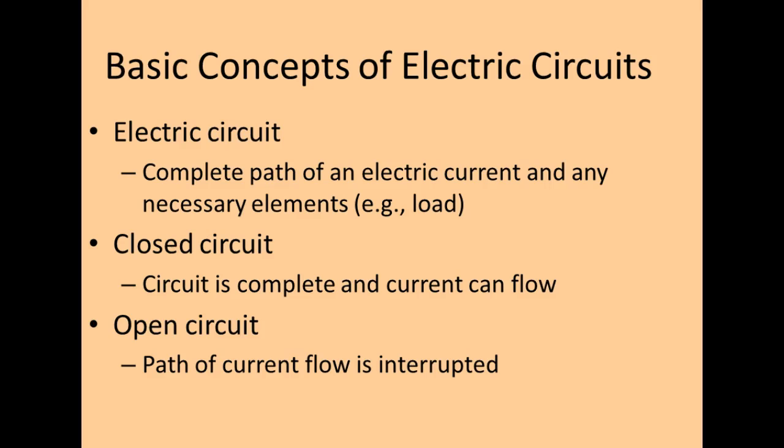There's resistance. We got 3 rules. All right. We said the one thing that stands out was what over here in the series? Our amps, all the same. Over here, voltage stands out. 1 is equal to 2 is equal to 3, etc. In other words, if I have a 230 total, this one's getting 230, this one's getting 230.